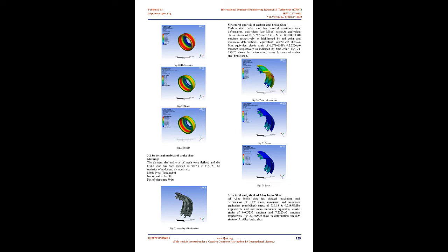Table 1. Parameters of brake drum design. Category: commercial heavy-duty light truck. WL, loaded weight, kg: 30,000. WC, curb weight, kg: 12,290. Vmax, km/h: 75. Brake surface diameter, mm: 420. Overall depth, mm: 241.3.